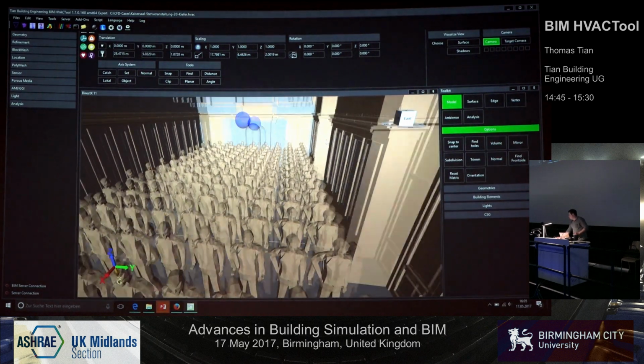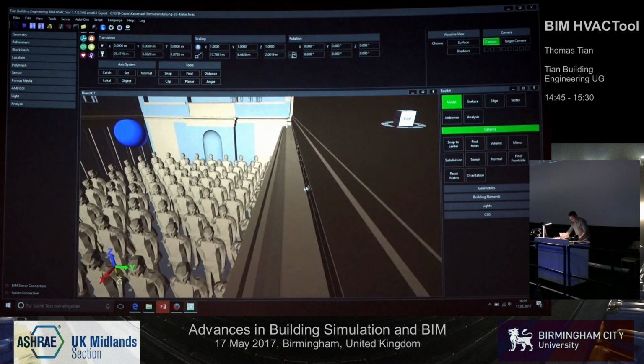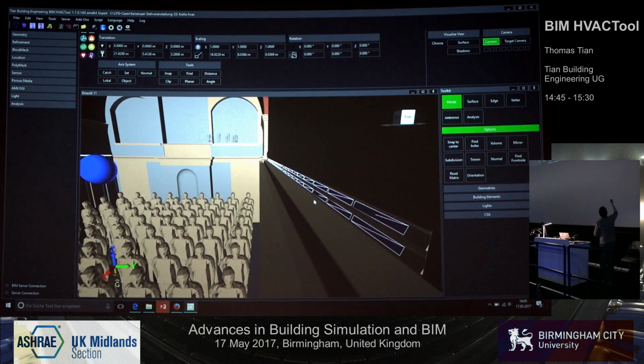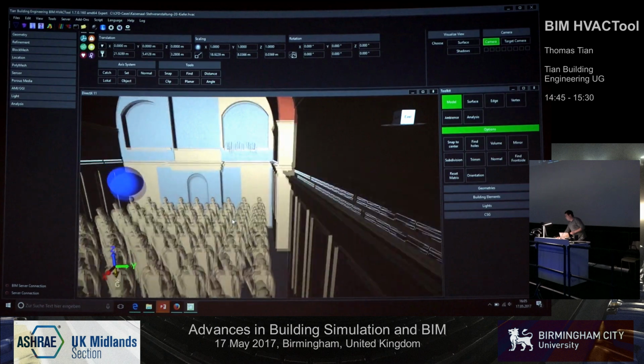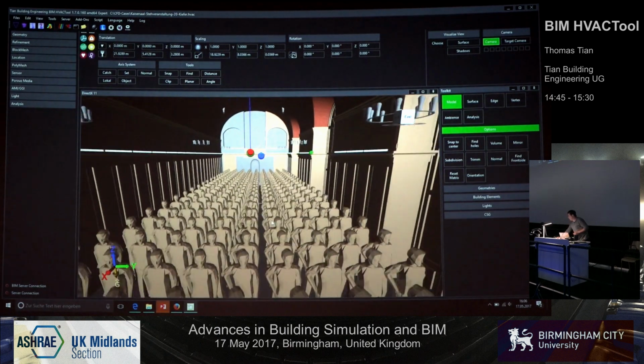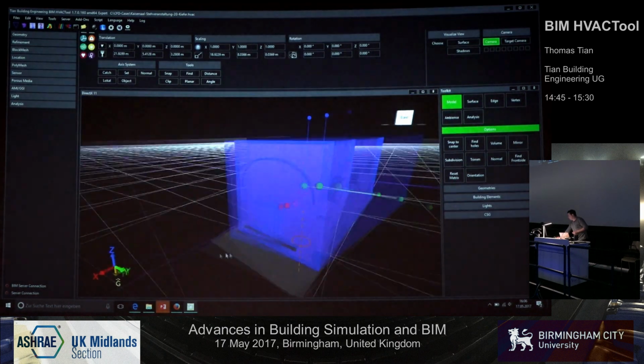And you see the room is very complex, and we have to find a way for OpenFOAM, because the fresh air is coming here in these small things here, and then you have a small mesh here, and then you push the air in the big room. So you need to find a way, okay, how can we set up refinements, how can we set up the boundary conditions? And this is one way of a building from our consulting. You see it's quite easy.